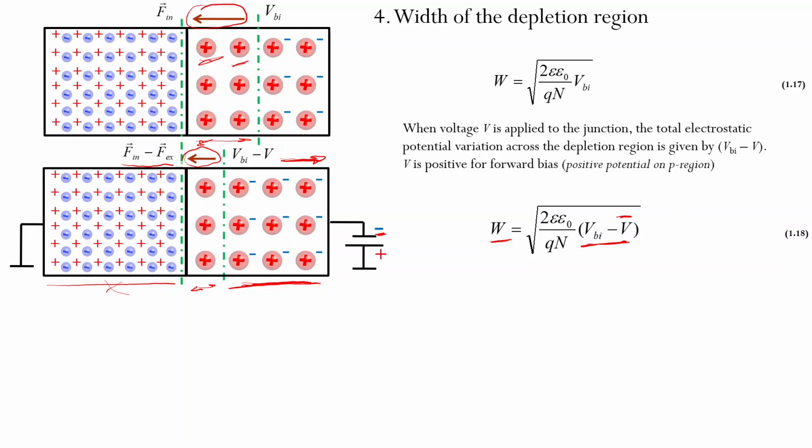That suggestion is quite reasonable, because for majority of semiconductor devices, the neutral region here is quite conductive in comparison to depletion region, obviously, and since we have kind of two resistors connected in series, this is a resistor corresponding to resistance of the depletion layer, and this will be a neutral layer.